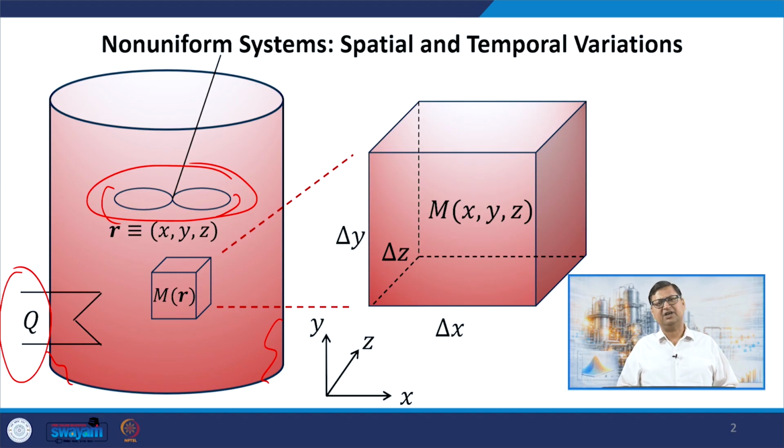What we call in chemical reactors as dead zones and things like that. So, you will have a non-uniformity in mixing. That can give you a density variation or concentration variation in the vessel. In addition, when I am heating it, you can imagine that the heating can also never be uniform. So, you can have variations in property like temperature throughout the vessel. Let us say, for example, the temperature near the wall will be more affected by the surrounding than compared to somewhere in the middle of the reactor, right.